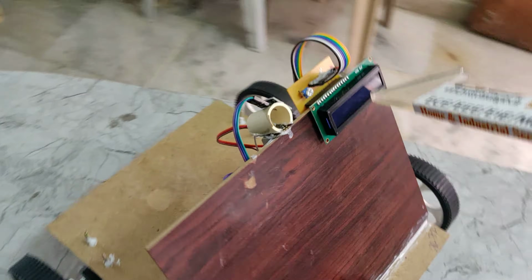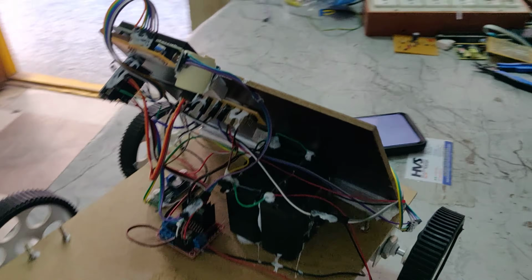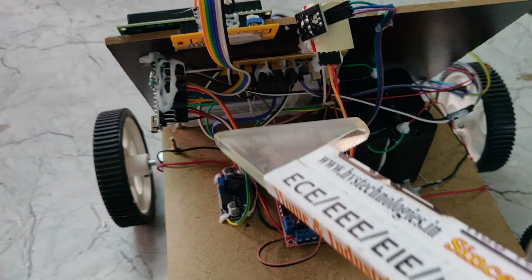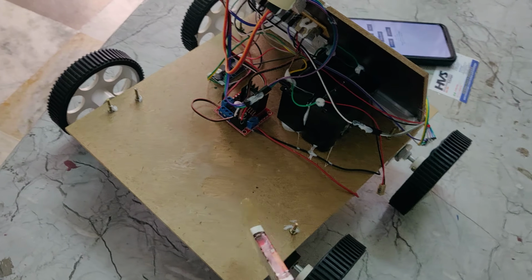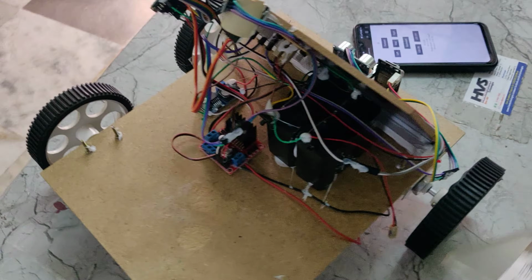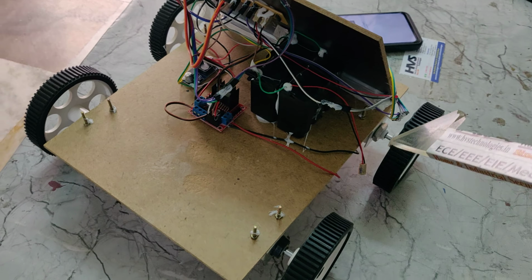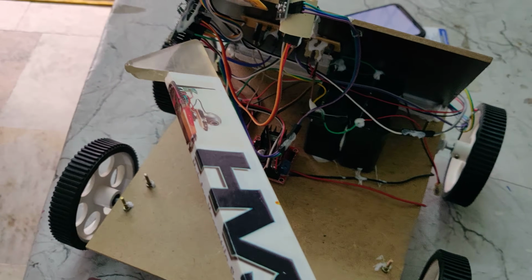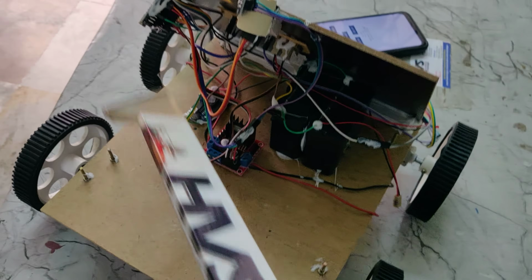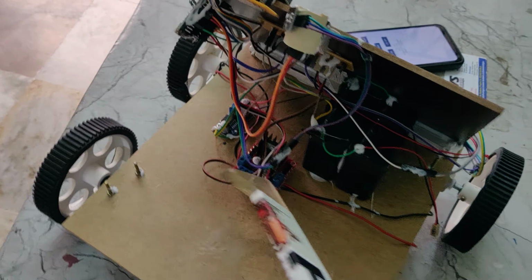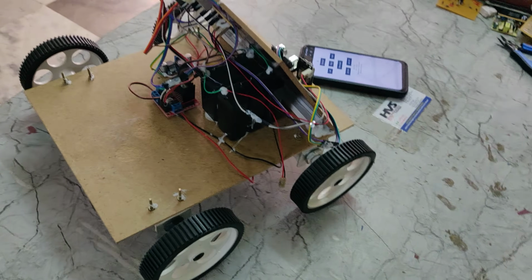The same will be displayed on this 16x2 LCD screen. These sensors and the LCD are interfaced to the Arduino board, which takes care of input from the ESP32 camera. The commands to control the robot movements are received by the ESP32 camera and passed to the Arduino Nano board. The sensors, the output modules and display, along with these two DC motors, are interfaced to the Nano board through this L298 motor driver, connected to the GPIO pins of the Nano board. The whole system gets power from this 12 volt 2 amp rechargeable battery pack.